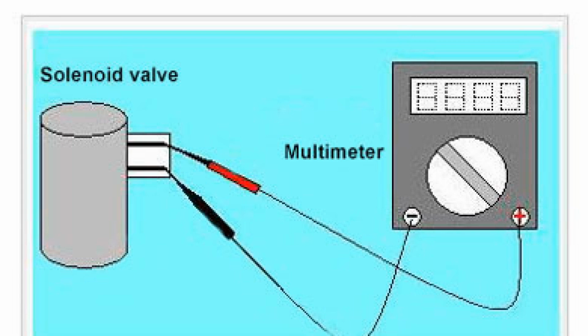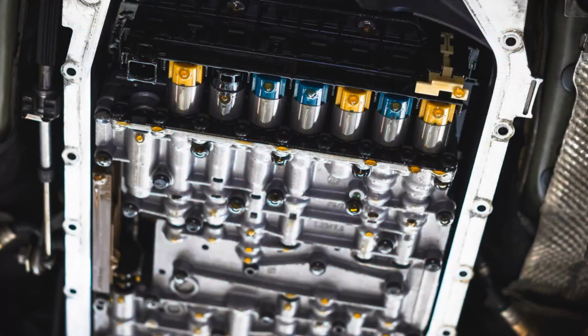And while the oil is cold, the solenoid copes well with its functions, but after warming up it starts to break. To solve this problem, it is necessary to perform the procedure of rinsing the solenoid. For this purpose, special washes, solvents, and cleaners are used. AC and solvent cleaning also effectively helps to cope with fouling.